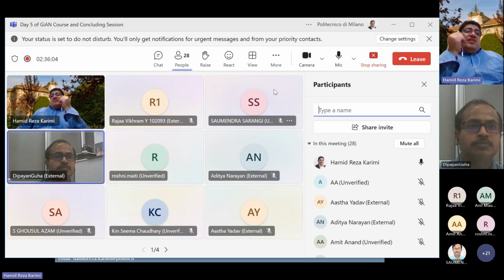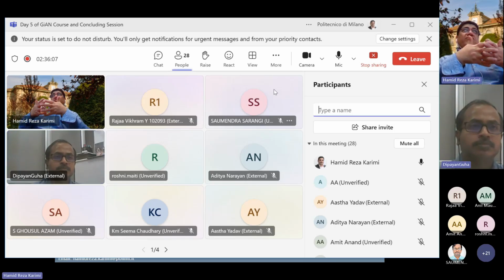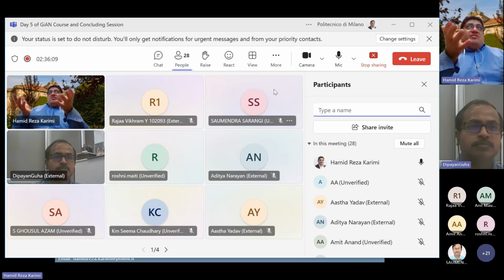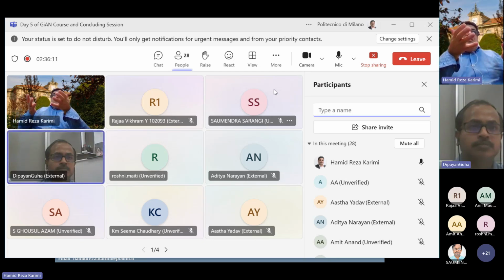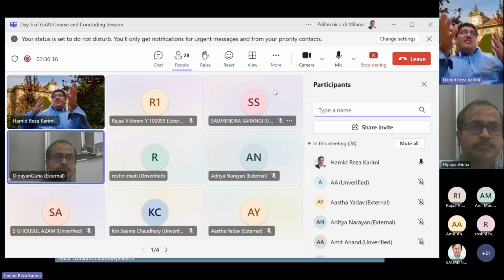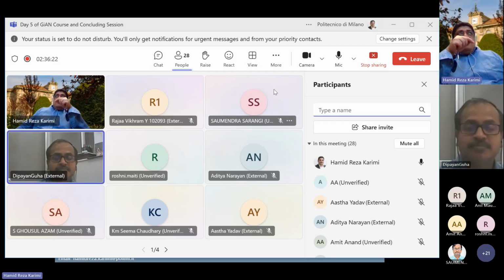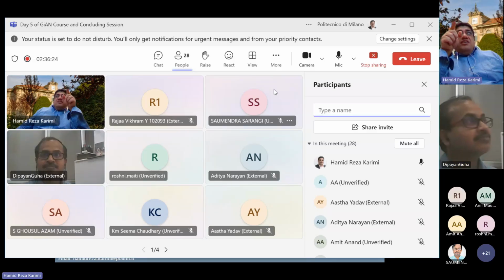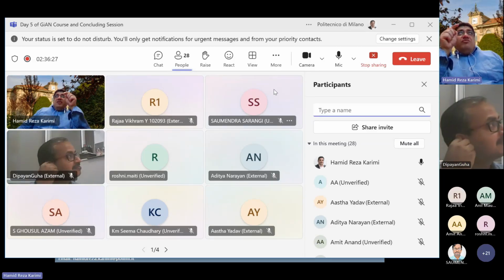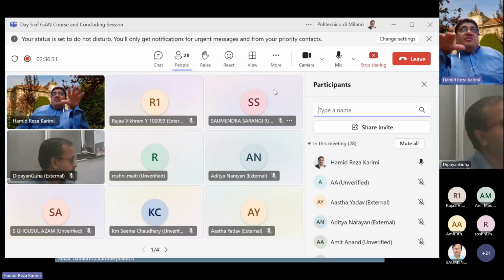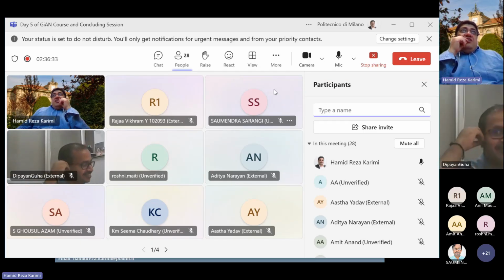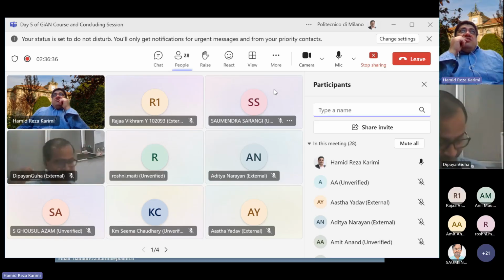So in fact, when your question is about the fusion, what could be fused? The LiDAR gives you one-dimensional data about the positioning with the distance to the respective landmarks. So you can develop some estimation tools, and at the same time, you can use the camera information for collision avoidance, if you have a time-varying environment. This could be a very interesting point.